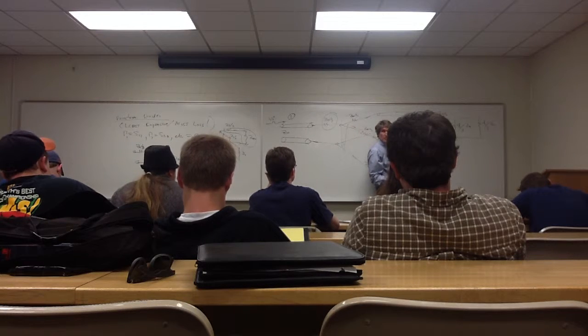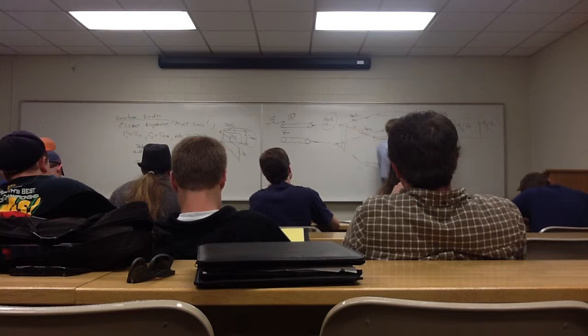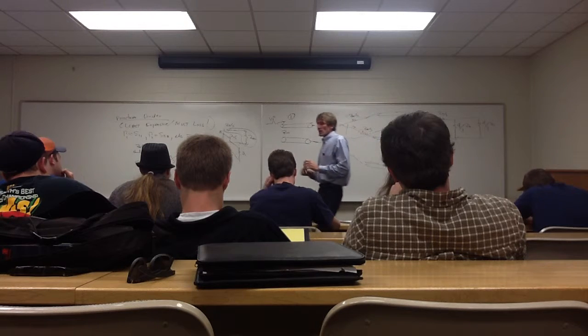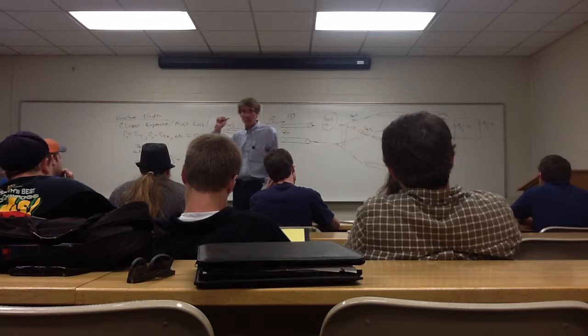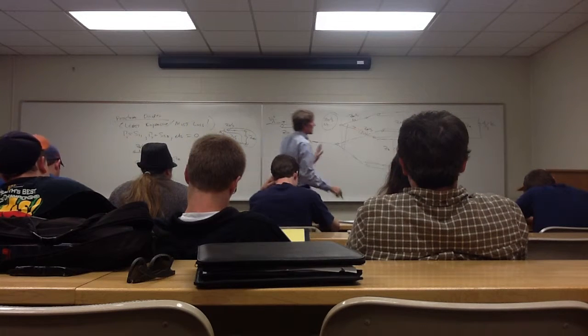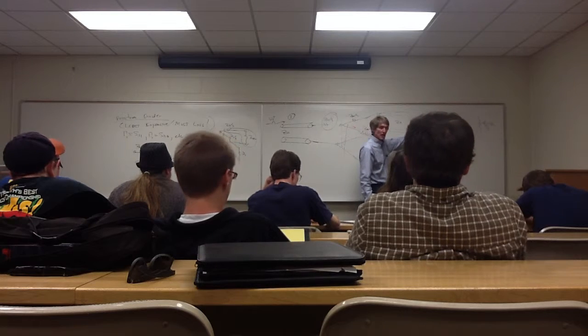You all agree with that? The two parallel resistors are going to have an equivalent of 2/3 Z naught plus 1/3 Z naught is going to be simply Z naught. That's the key. With that, we know what we've got there is something that's going to be impedance, looking in here, I have an impedance of Z naught, correct?